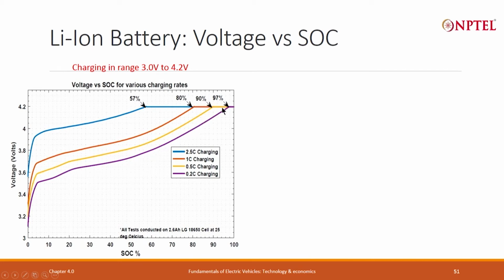you actually try to charge it using what is called constant current. So, in the charger, the voltage is continuously varied. The voltage is applied, for example, in the beginning you may apply for a cell, if you are charging close to 3.5 volt, and you will find out what is the current. If the current is less than 0.2 C, you will increase the voltage slightly. If the current is more than 0.2 C, you decrease the voltage. So, you decrease voltage, and the charger can do that more or less automatically. So, that you track the voltage and you keep on charging.